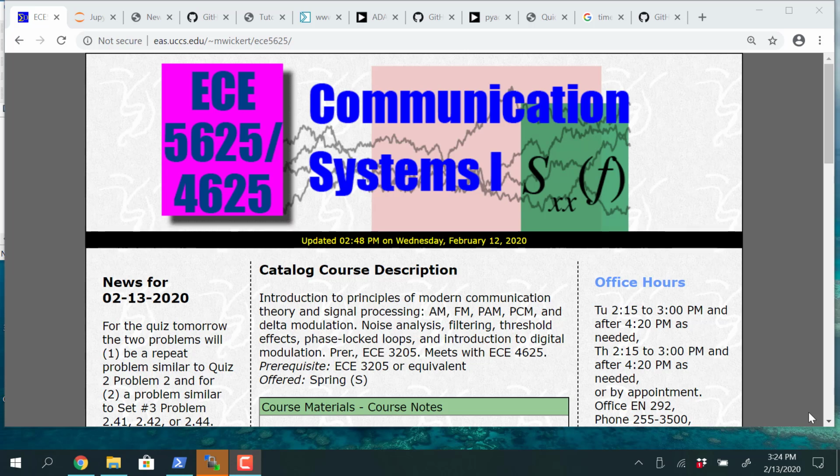Good afternoon. We're already in the midst of a discussion because we just picked up the quiz, and John, since you've already had the quiz, I can talk about it right now. At least I did see that you emailed it to me before I came down to class. So the question is on number 2, the periodic power signal that had a power spectrum. To get the average power, you just integrate that, and it's integrating 3 delta functions. Do you remember I said that's the shifting property, so that's easy to do. That would just be the sum of those values, right? So it's just 40 watts, right?